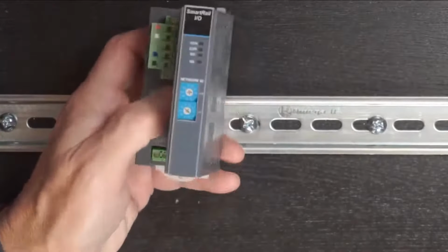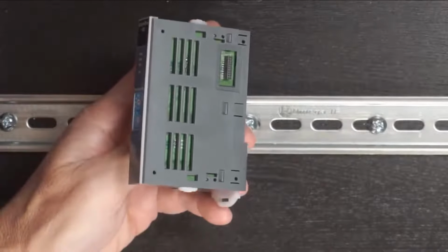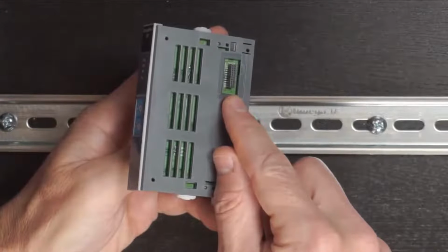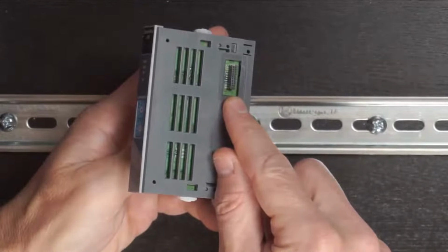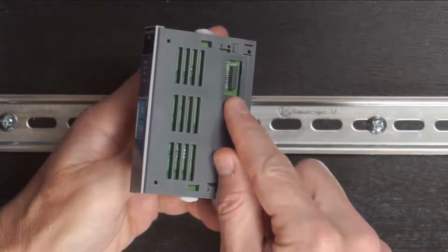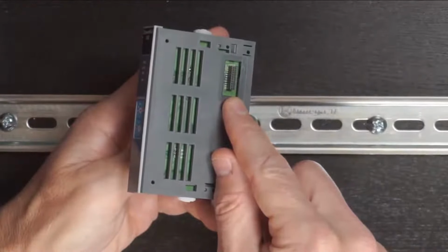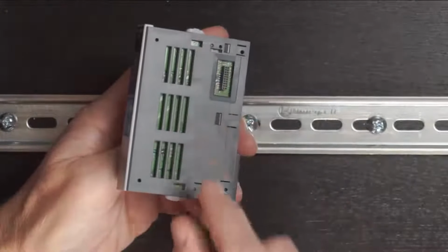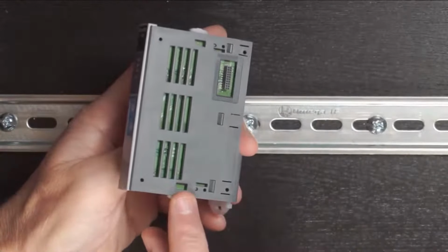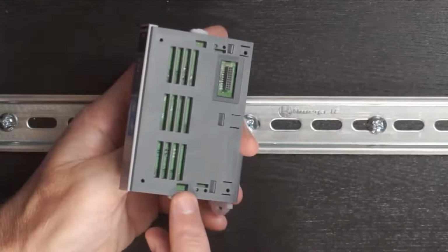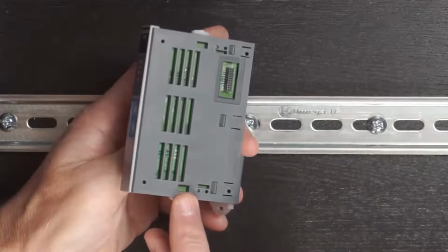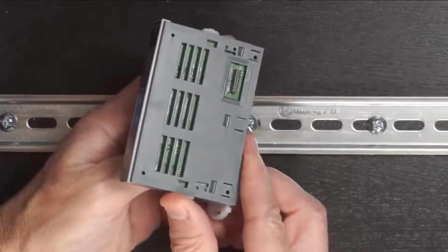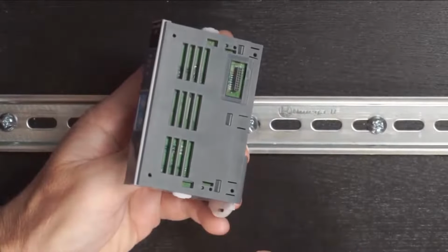So let's turn it over and take a look at the right side of the base. So we've got our backplane connector. All the modules have a backplane connector in this approximate position here, and the backplane connectors just effectively stack on top of each other. We also have openings or slots at the top and the bottom of each housing, and we start with the base, where a hook in the next module will be inserted. And then once that hook is inserted, we've got a latch at the top and the bottom that will be moving into position to lock things into place.